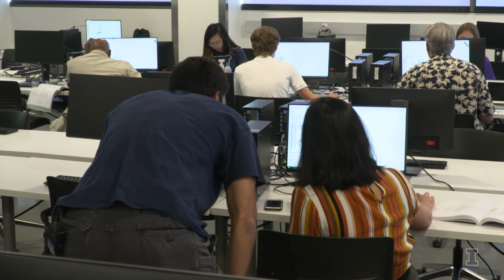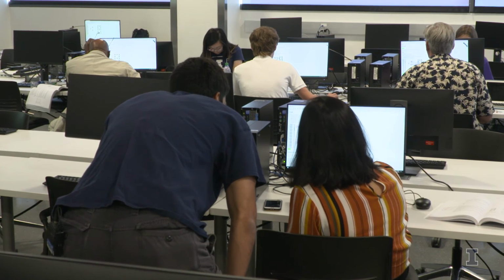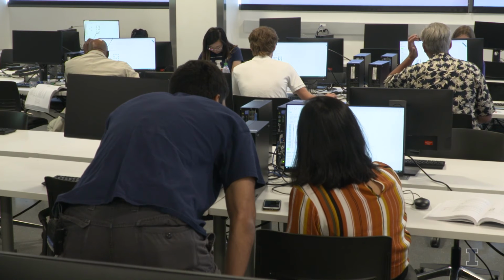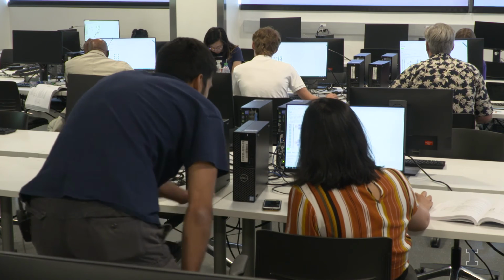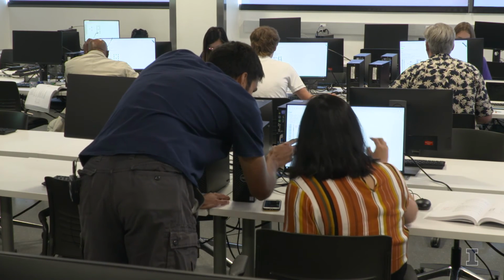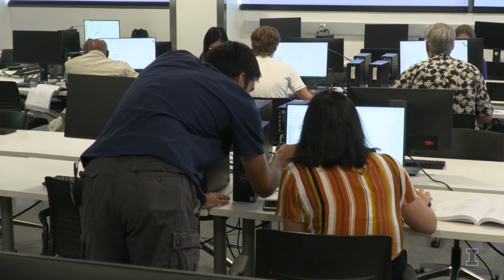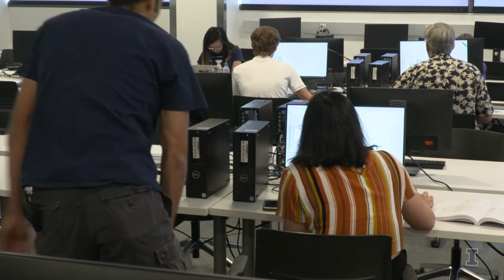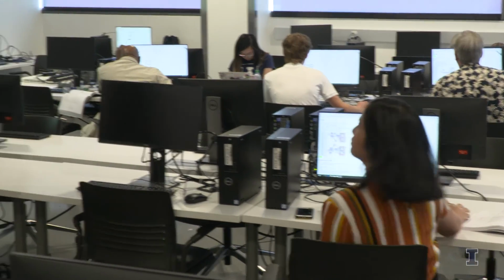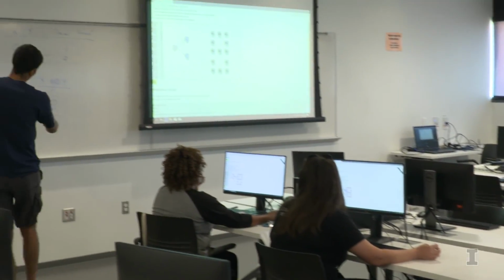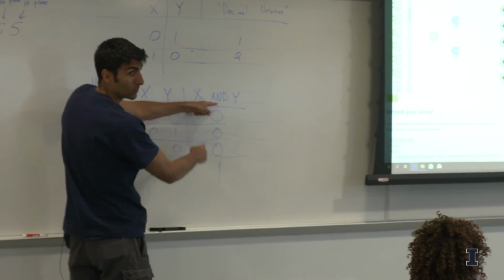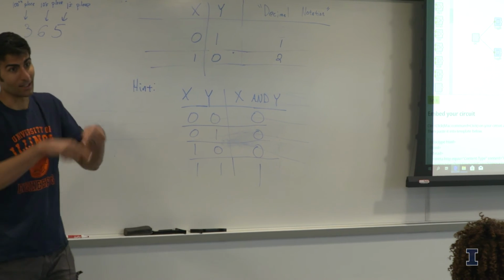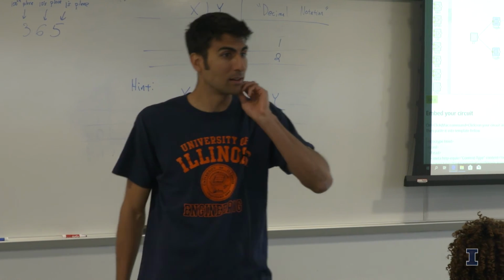To be 2. So I managed to do it when one of them is on, but because of this one, I figured you need it for 1, 0, and 3, but not for 2. So when they're both on, then you want this middle one to go, right? So what you could do is, that looks a lot like this AND, right? This is saying that when they're both on, you have that. So if you hook them both up to an AND and then you plug that to the middle one, you'll get what you want.